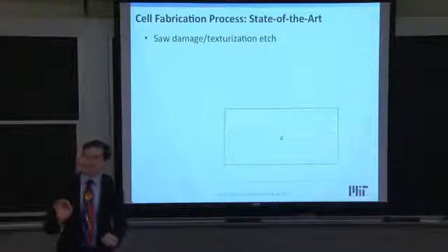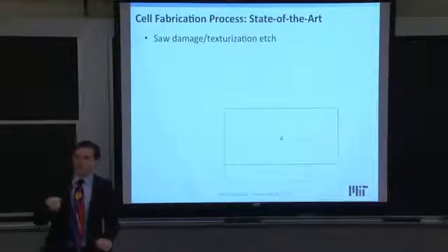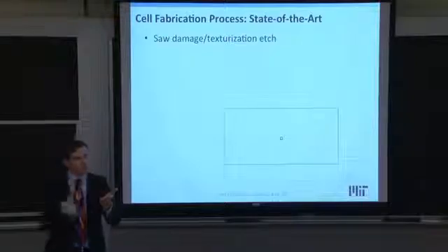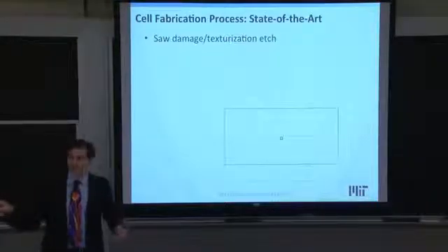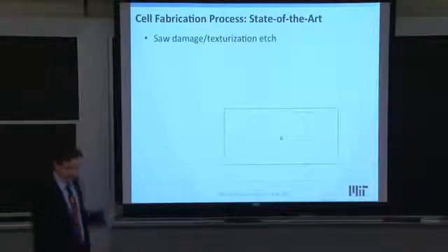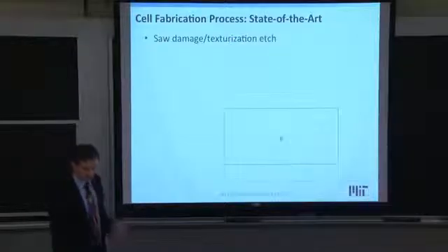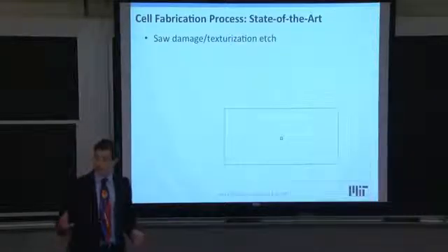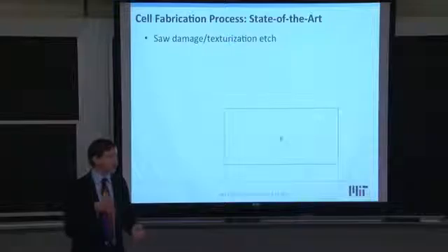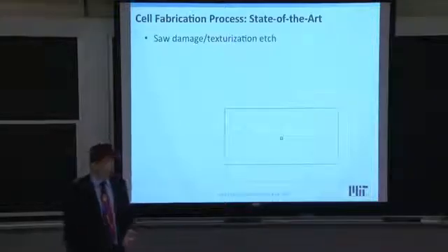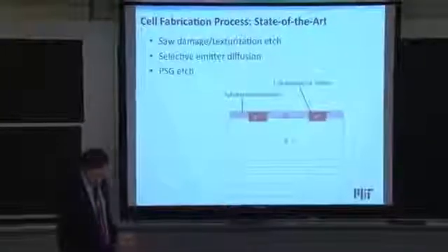And you can take advantage of the subsurface damage by etching it in such a way that you etch along the damage and form texturization. So it's a bit of a 2-in-1 here. You clean the wafer, you create your texturization, and you remove your saw damage so that when you lift your wafer, the wafer doesn't break because there's some hairline fracture caused by the silicon carbide grit.